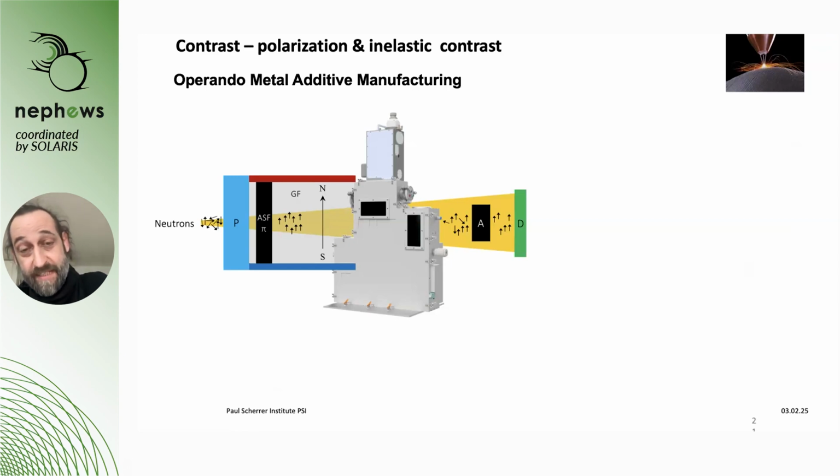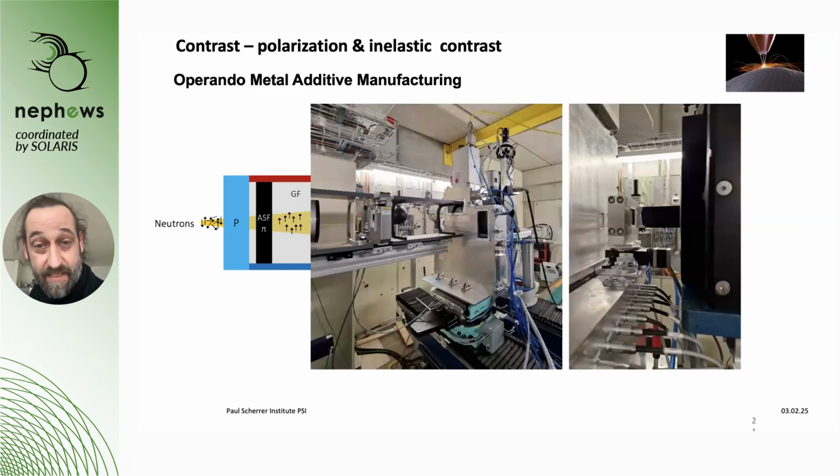And ferrite is a magnetic phase, and that means with polarized neutrons we become sensitive to this phase in particular, because when you have a ferromagnetic phase, it will depolarize the beam, and the more ferromagnetic phase, the more depolarization, and only in these places, of course, where you have the ferrite. And so this is how our setup looks.